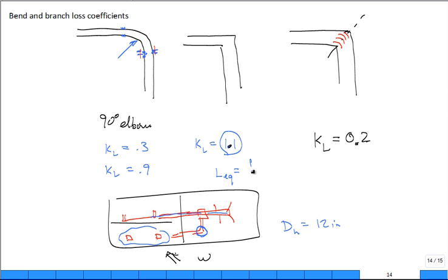You had friction factor, diameter, what was it? Is it K, diameter, friction factor, right? So the nominal friction factor, I forget what it was, 0.02. So the nominal friction factor 0.02, the diameter was 1 foot, the loss coefficient was 1.1, okay?